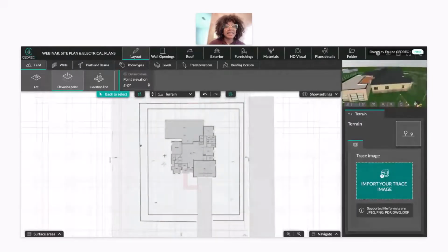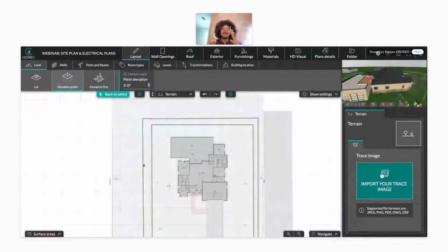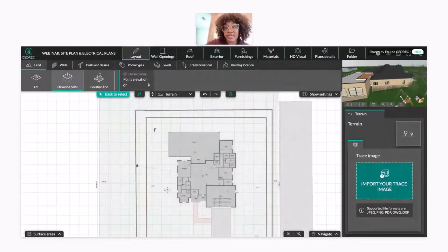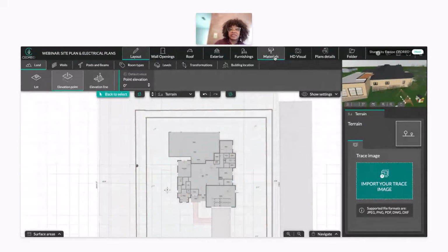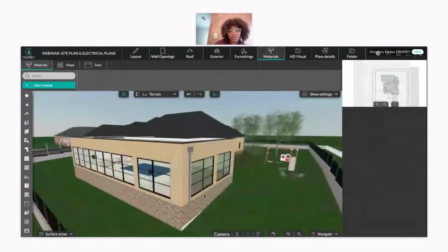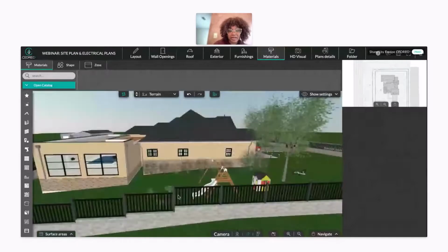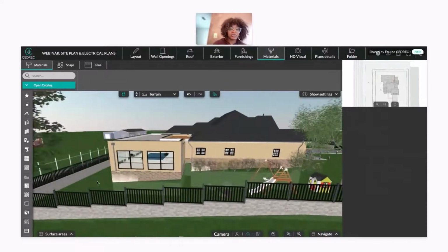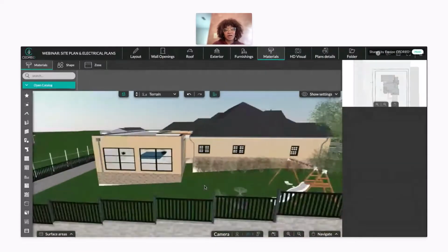That's because in the back, I need to set the elevation in the back, which is lower than the elevation in the front. So now I'm going to change this to 0. And then I'm going to add 0 back here and back here. And once I do that, you see how now I have this sloping environment coming up. So this is 5 feet up here, and then this is sloping down here. It's exactly 0. So it's flat ground down here.